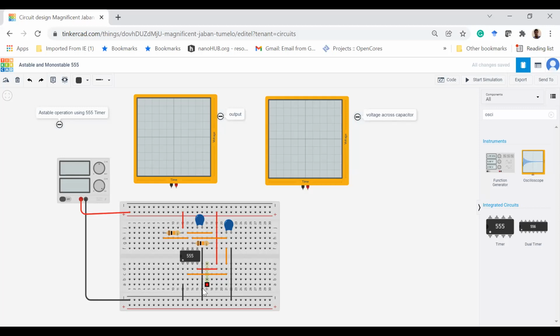So pin number 2 is connected here with pin number 6. Just check, and this capacitor is there, connected to ground. And we have another capacitor connected at pin number 5 to eliminate noise, a denoising capacitor of value 10 nanofarad, connected to ground. So let's pick a value for this one: 100 nanofarad. Okay, fine, I'm taking the default value.